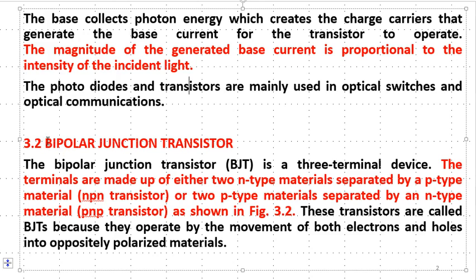So now let us go back to the basic bipolar junction transistor, which we said has 3 terminals, and the terminals are called base, emitter, and the collector. And how are these terminals formed, or how is this transistor designed? Normally they get a piece of pure wafer of either silicon or germanium, and at one end they inject it with either n-type impurity, that is group 5 elements, or if they wish, they can inject it with group 3 elements by the process we call doping.